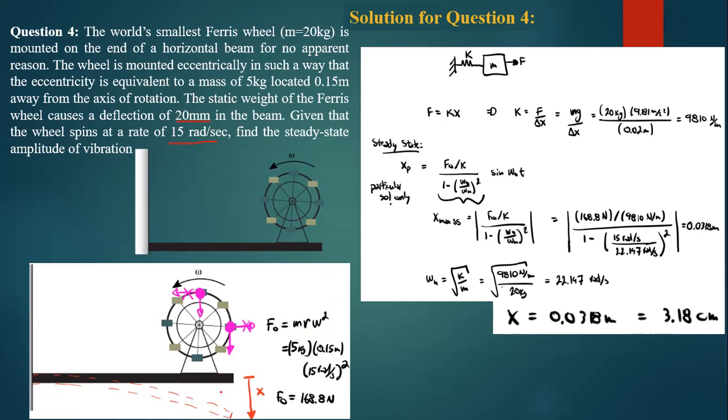This force produces vibration, and there is already a static deflection of this beam initially due to the static weight. It is already given, 20 millimeter. Now, modeling this beam as a spring carrying the mass m, the combined mass acts on the beam, so the beam will deflect, and the beam itself is an elastic beam with some k value.